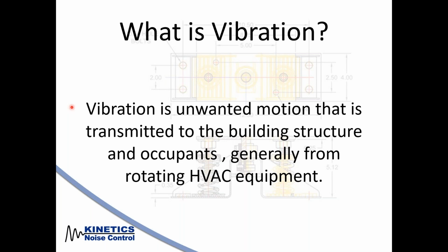And also the main overlooked part of vibration isolation isn't just the noise it makes, it's the fact that modern commercial buildings are made up of structural columns that are steel, and that vibration can get into the steel structure of the building and actually cause a tuning fork effect, and you can actually see degradation and damage to the building structure over time when it comes to this vibration getting down into the building.